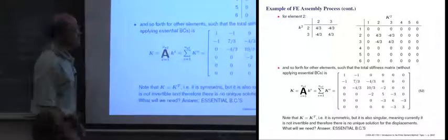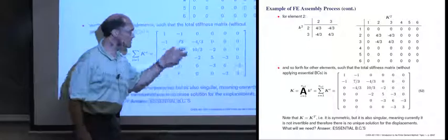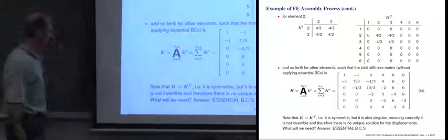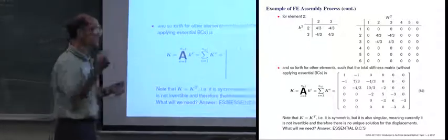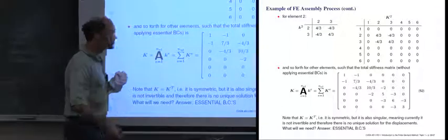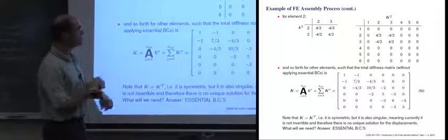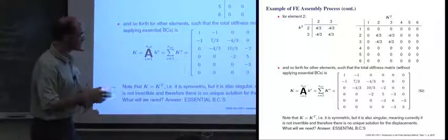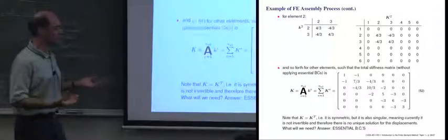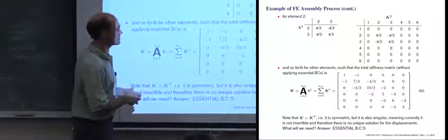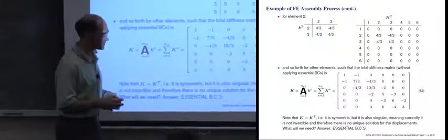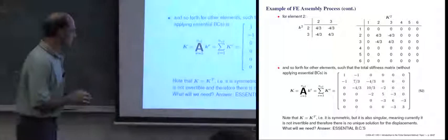Okay? You'll see it's symmetric. It's symmetric for 2 reasons. Number 1, we assume the same shape functions for the displacement degree of freedom as well as for the weighting function. But also, well, here it's scalar. But later on, when we get to more interesting materials problems, it also is eventually going to relate to what's called the constitutive model itself.